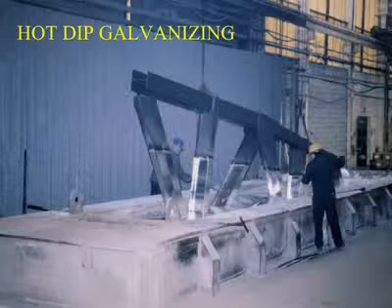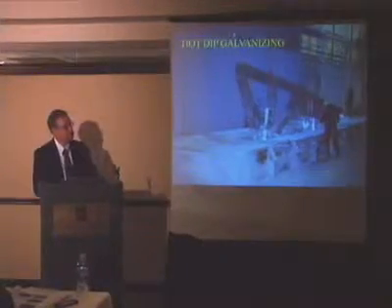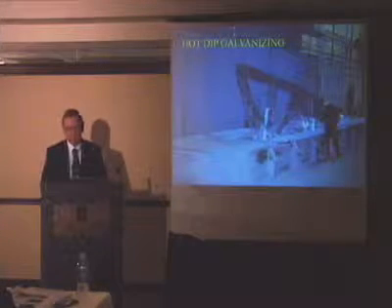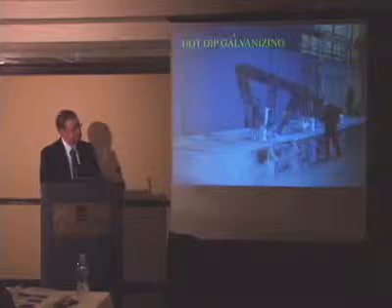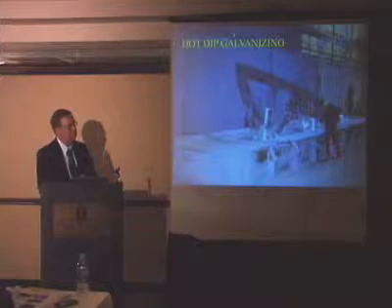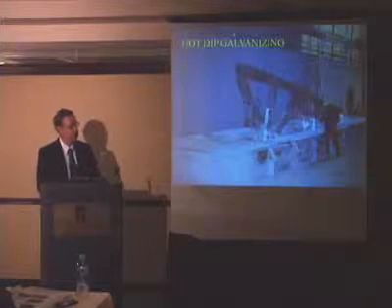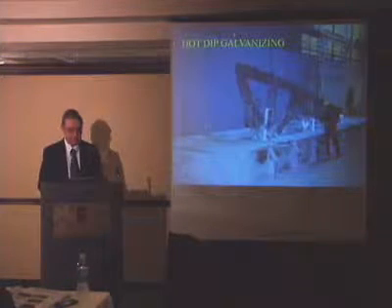One thing that's come up in the past 15 years is hot dip galvanizing of truss sections. These sections can be fabricated in the shop in modular pieces that will fit in an available tank. This section is being dipped in a 60-foot long tank. It's about 7 feet deep, 5 feet wide, so only half of the truss can fit down in the tank.